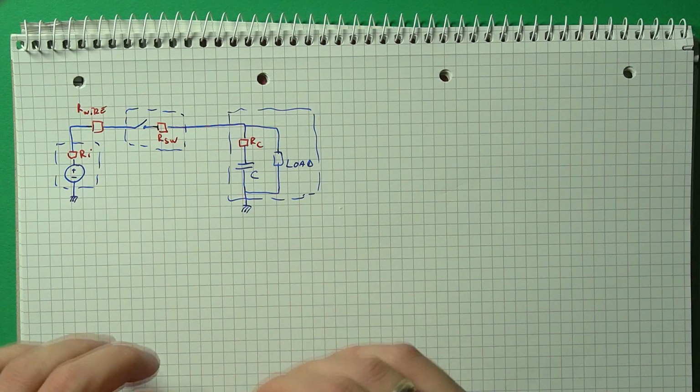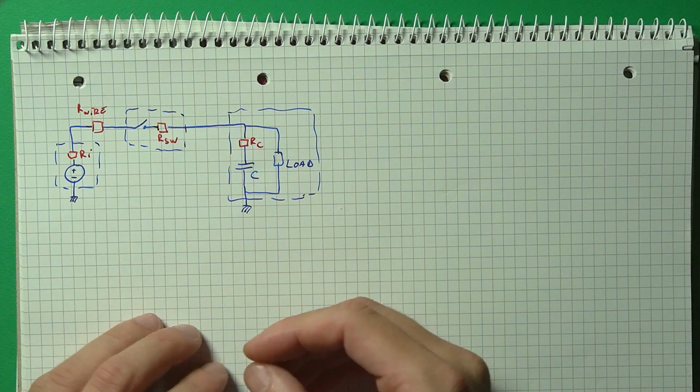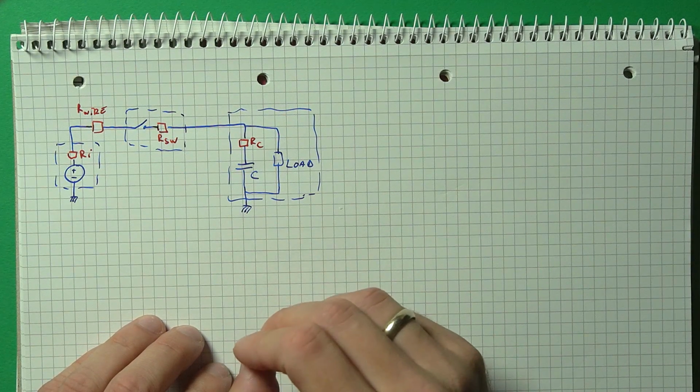So this covers the main ways in which a switch can be protected when it's driving inductive loads. You can have other components involved, but these are the basic principles. Next, we have the topic of capacitive loads. Here we have a bit of a problem. The common practical way of limiting the inrush current is by adding resistance.